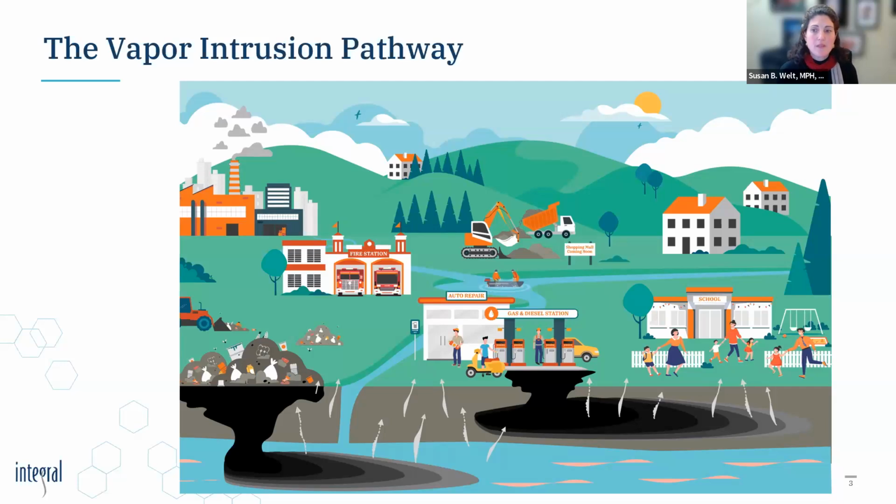As we know, the vapor intrusion pathway occurs when vapor-forming compounds in the subsurface migrate through preferential pathways into overlying buildings. These compounds can be naturally occurring or from manufacturing operations and include semi-volatile organic compounds, volatile organic compounds, mercury, methane, radon, and some PFAS, pesticides, and PCBs. And very low concentrations in the subsurface, even below drinking water standards in groundwater, may pose an inhalation risk to building occupants. As a review, the vapor intrusion pathway consists of 5 elements.